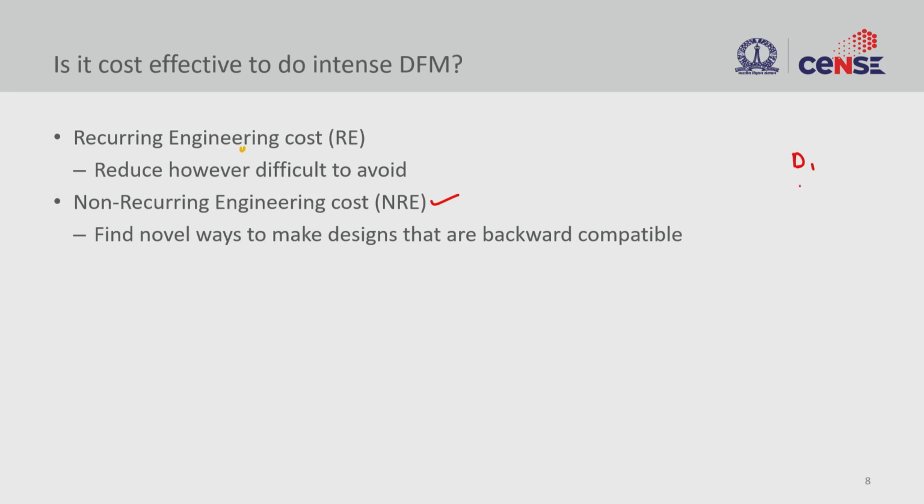and then if you are going to device D2, you share the majority of layers and structures that you have developed for device 1 for device 2 in terms of layout, right? Let's not worry about if I have a gate thickness variation between D1 and D2, this is not going to affect too much of your layout. If the line widths are maintained, then you are okay.